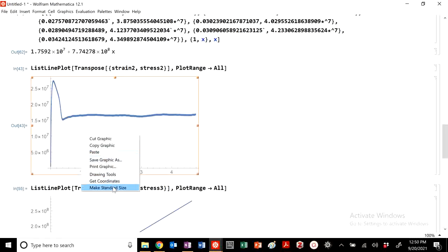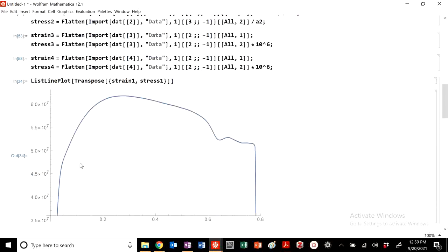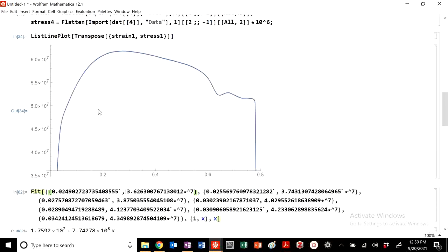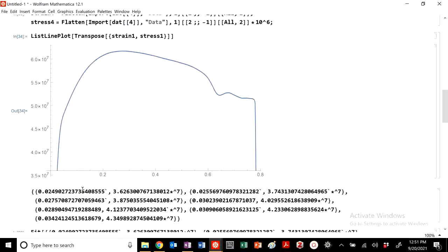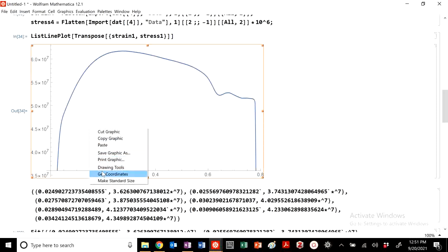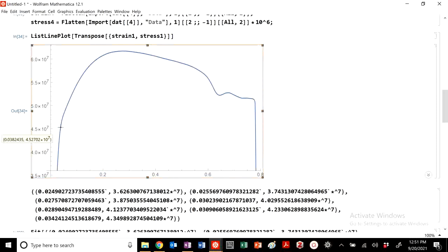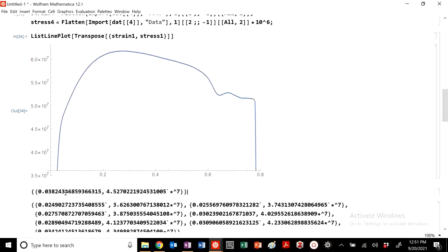Let's do the same thing for here. But again, I already know what this material is. So again, I could calculate my Young's modulus like this. I could pull out some values. Once I start to lose linearity here, I'm going to grab that. That's kind of my yield stress. So, oops, should have copied that. Grab it, copy, Control C. So this would be my yield strain. This would be my yield stress.